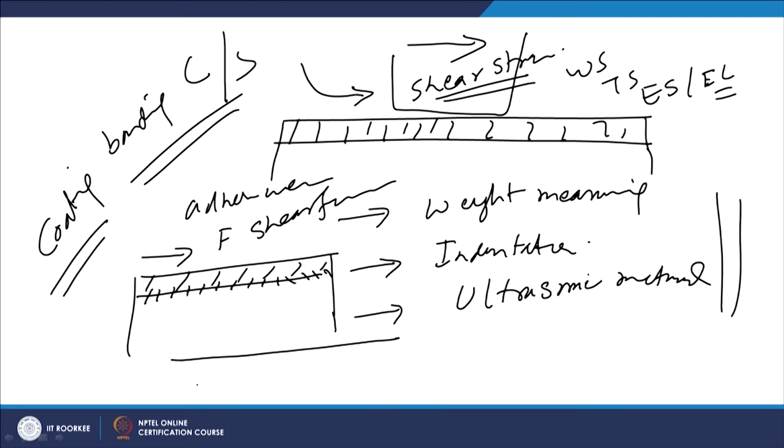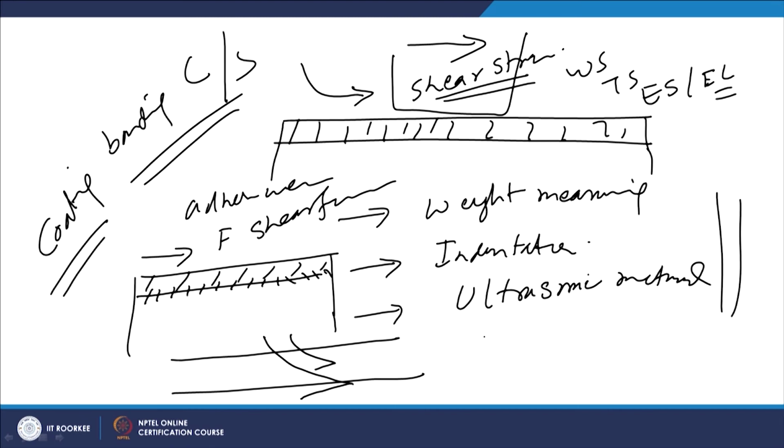and that is why, for the given loading conditions, if the maximum shear stresses are acting within the coating, then it is fine, probably the coating can sustain those shear stresses. But if the maximum shear stress level is occurring at the interface, then chances for the removal of the coating from the substrate become high, and therefore, in light of the location where the maximum shear stresses are acting in the modified zone, we need to take a decision about the thickness of the modified zone.